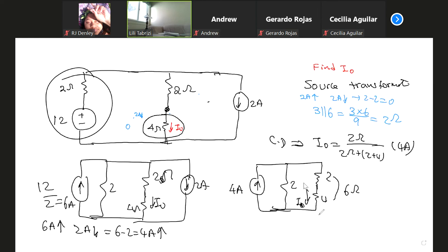In order to practice nodal and mesh, or review actually, I'll do the same problem with nodal and mesh. Professor? Yeah. Should source transformation be the first thing, the method we think of before we try anything else? It depends on the person. I always think about source transformation immediately. Anytime they ask any circuit question, before I jump to anything, I think, can I use source transformation to get my answer? And if so, I just do it by quick change.